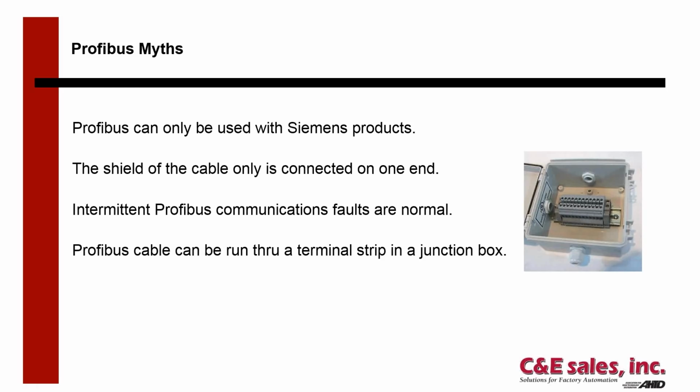We do not want Profibus cables landed on a terminal strip in a junction box. If you're listening to the sound of my voice and that's happening at your facility, that's something that you need to address as soon as possible. That's a huge source for noise and reflections.